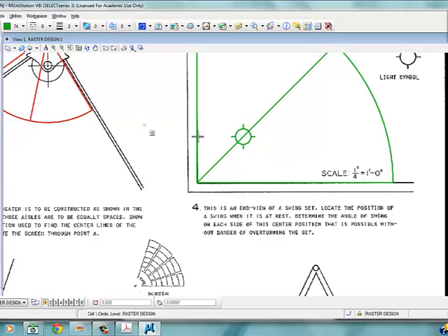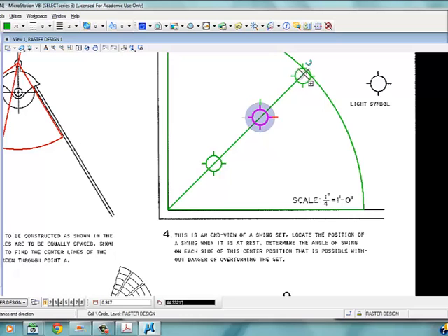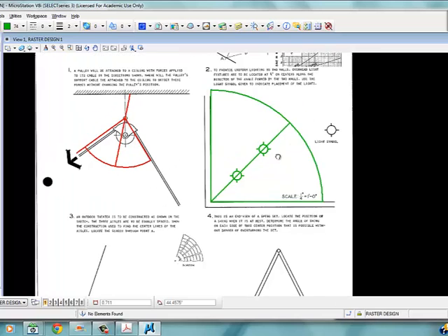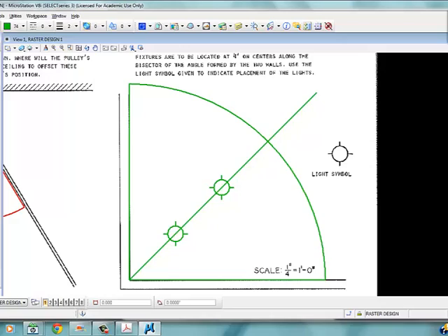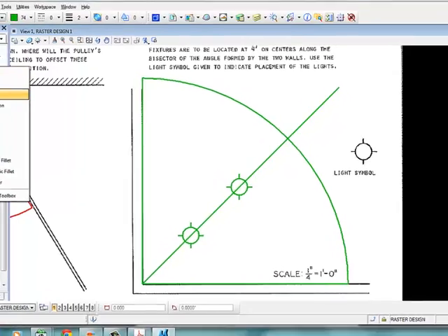Now I'm going to take my copy tool, find it again. Now I type in a distance of 1. Hit the tab key so it moves it over into the angle. Hit N. There's the second light. I don't know how many lights they wanted here. We'll put one more. But what I want to do is extend this line out a little further. We'll go to our copy. 7, 3 is our extend line.